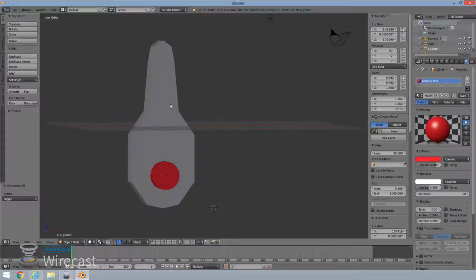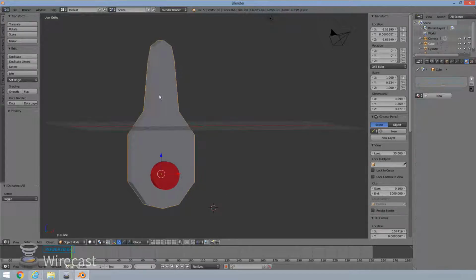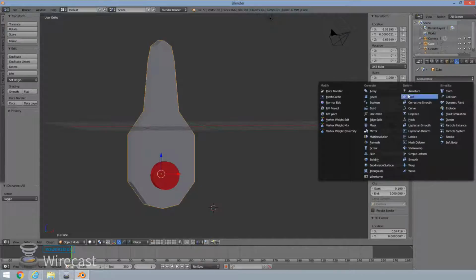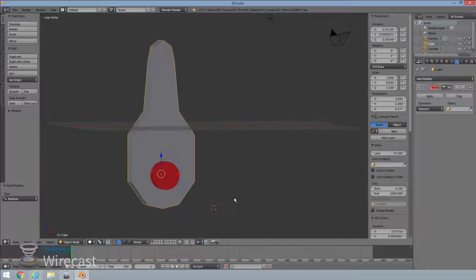In this case, the hole that's going to be cut out is going to be cut out of the slack adjuster. So I'm going to select the slack adjuster, go to my modifier button over here, select it, expand this drop down box and find Boolean Modifier, which is right there. Now there's a couple of settings. Here you'll go down to find the type of change you want to make. Now there's 3 different types. I'm going to use difference.